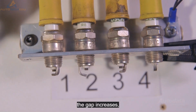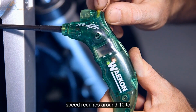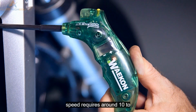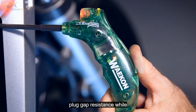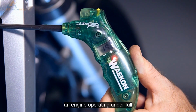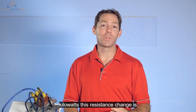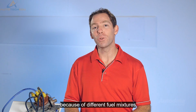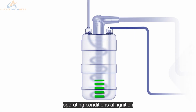As the resistance of the gap increases, the energy needed to arc across the air gap must also increase. An engine operating at idle speed requires around 10 to 12 kilovolts to overcome the plug gap resistance, while an engine operating under full load may require around 20 kilovolts. This resistance change is because of different fuel mixtures and cylinder pressures under different operating conditions.